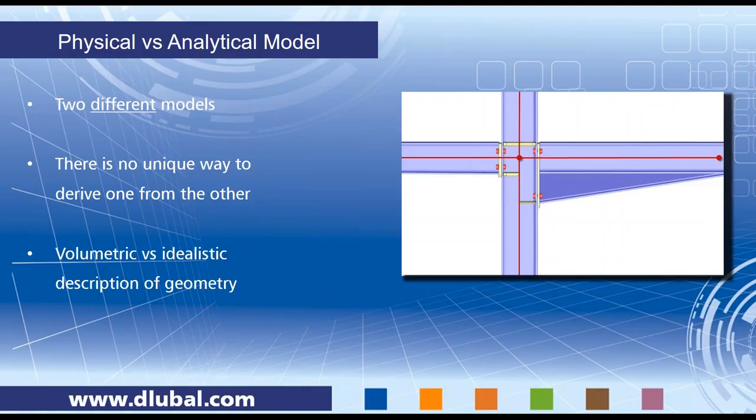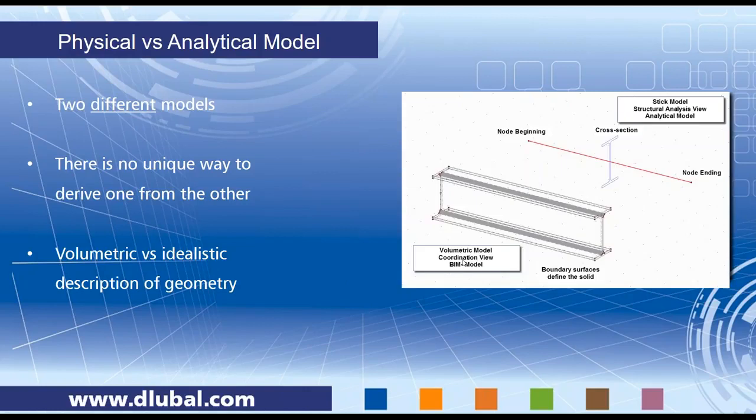And the second thing is typically when we have a CAD application or a BIM software, we have a volumetric view, and it means that boundary surfaces define a solid, and we get the real geometry of this structure, while in an analytical software, we typically would describe this beam with a node of beginning, a node of ending, and a cross section that defines the stiffness and also the resistance of this structure.